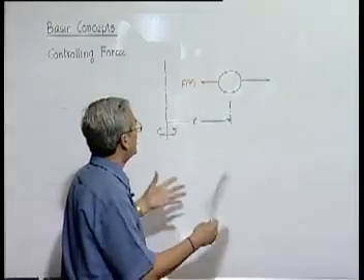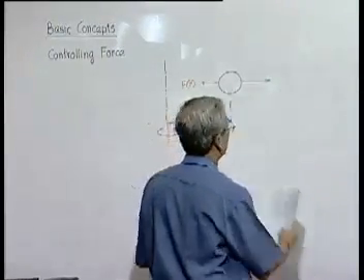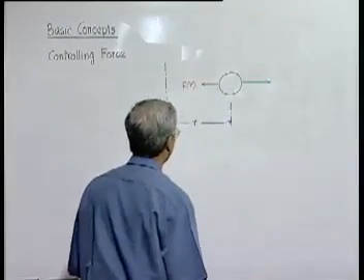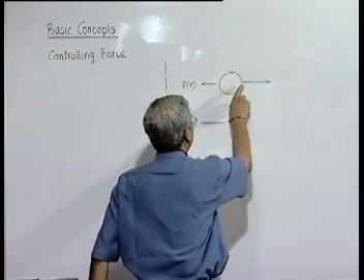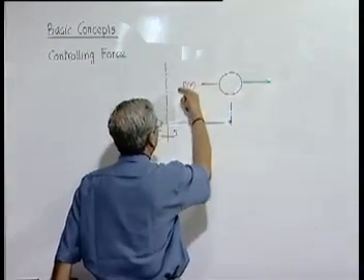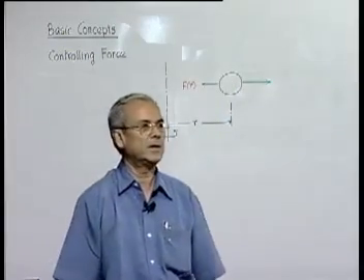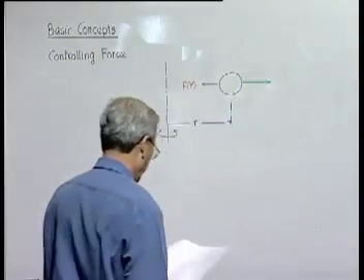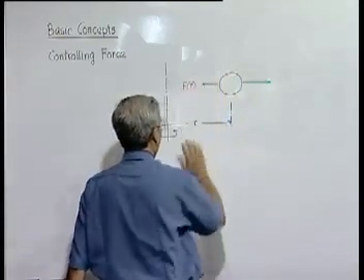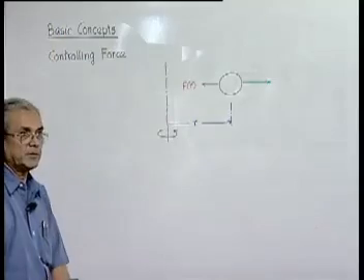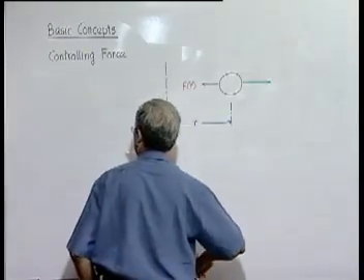We can treat that rotating, non-inertial frame system as an equilibrium system if we consider a centrifugal force. That means, when the centrifugal force is equal to the controlling force, this sphere is going to remain at this location, that is the equilibrium position. Therefore, this controlling force of a governor is a very important concept, and it dictates lots of characteristics.